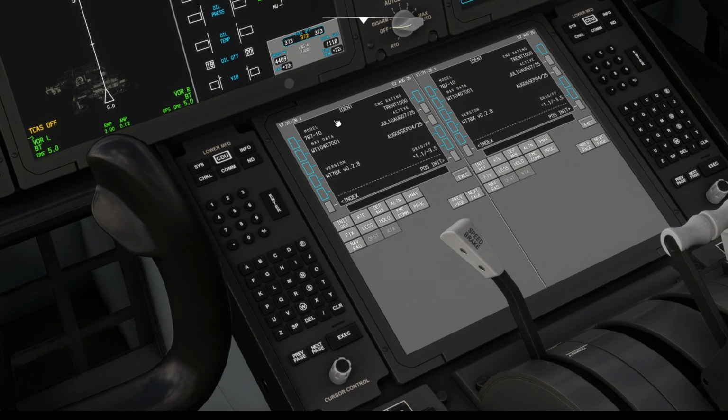So usually on the ident page we check the model 787-10 and the Trent 1000, and this is really important here. You want to check that you have an active database which matches your current date. So today, I think when I'm recording this, is like the 2nd of August. So July 10th until August 7th. So we're good for now.